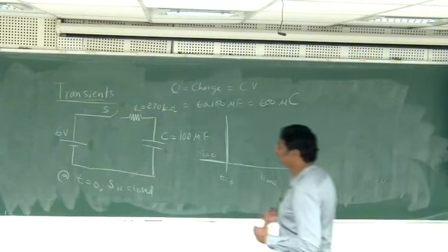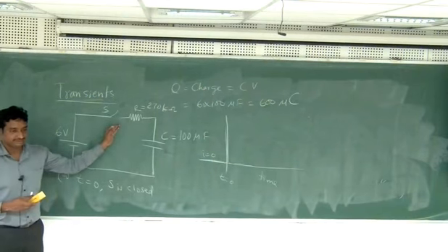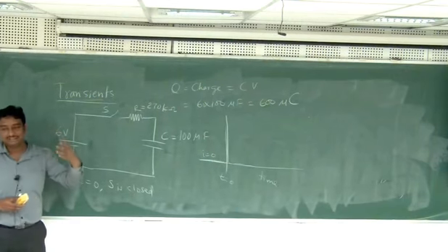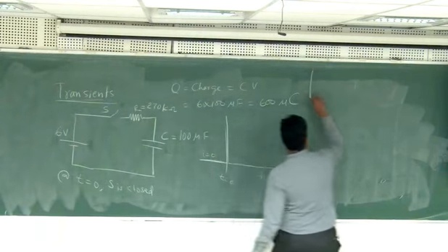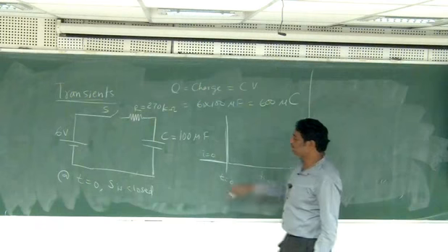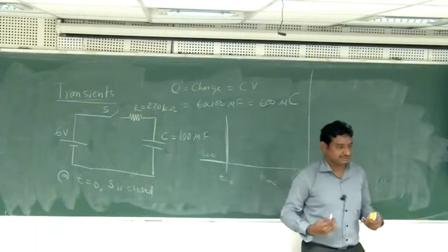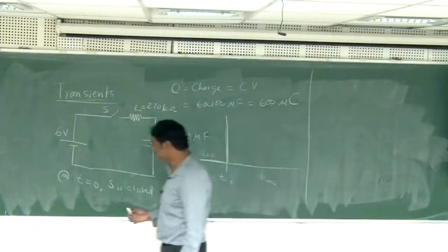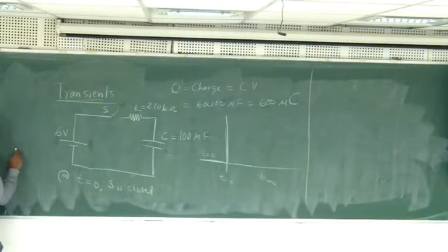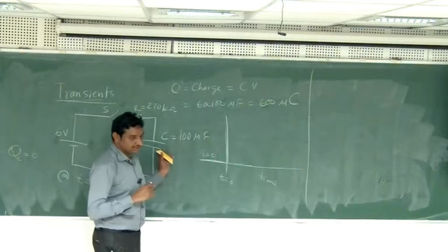Some of the answers here say it is 6 by 270. Then that will be the starting value of the current. It's actually correct. So what you do is assume that the capacitor is short circuited, because it is ready to get charged. Before time t equal to 0, it is also given data that QC equals 0. That means it is initially not charged at all.